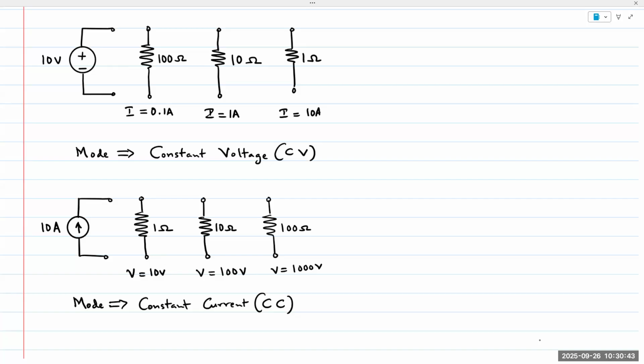The power supplies that we have in the back have the same thing. I think it's the bottom. I can't remember on this one. These ones are new. But somewhere on the front panel, again, there is an LED indicator that says CC and CV. That's how we know whether it's a voltage source or a current source.